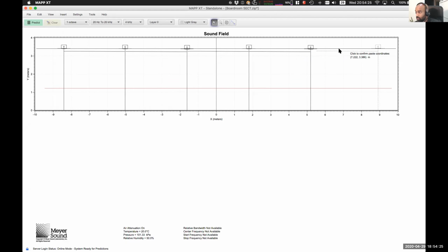And there you go. So according to this, I need 6 loudspeakers to cover this space. You can also select all the loudspeakers together and roughly center them. You can, of course, fine tune them and spend more time, get into the smaller details. But I'm trying to show you the quick and dirty way to get pretty close to what you would do in the final design. Now, this is pretty much centered, so I'm going to leave it as it is, or we could have just selected and moved all 6 speakers around.